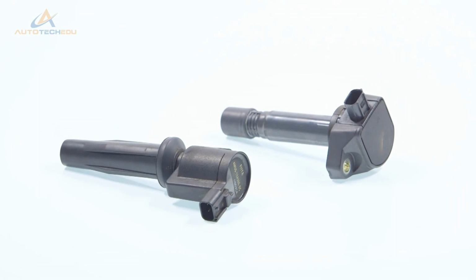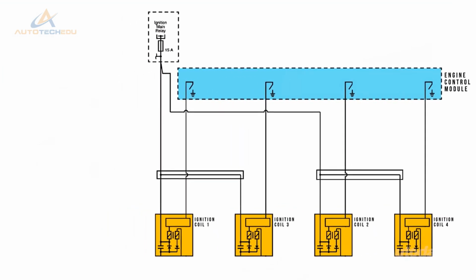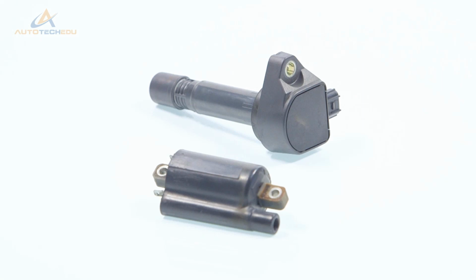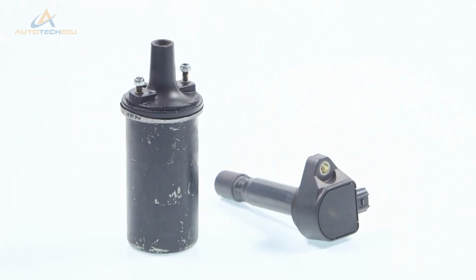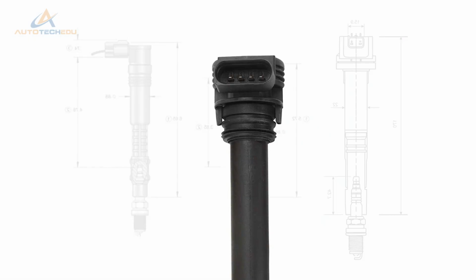There are two common types of coil over plug ignition coils in use today. A standard type coil over plug has two primary terminals only. These operate identically to a conventional coil system, using an ignition feed to the positive side of the low tension circuit and the trigger signal on the negative side. The secondary circuit is identical in design but can be constructed much smaller than a conventional barrel type coil. However, this type of coil over plug requires heavy-duty solid-state drivers to trigger the primary circuit. These may be identified by the number of terminals in the harness connector.